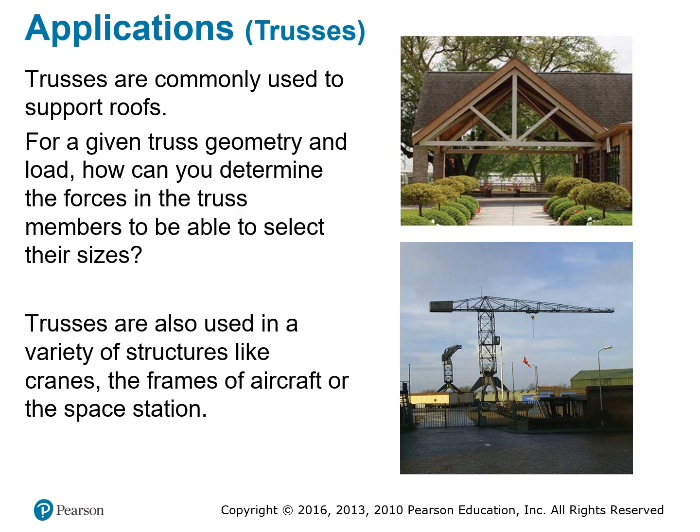To do that, you have to analyze, and you have to make some assumptions. For example, you want to design a house that can support a certain amount of wind, and the wind is going to give a wind pressure. The wind pressure can be converted into a wind load, and then we can design the proper size of the structure.